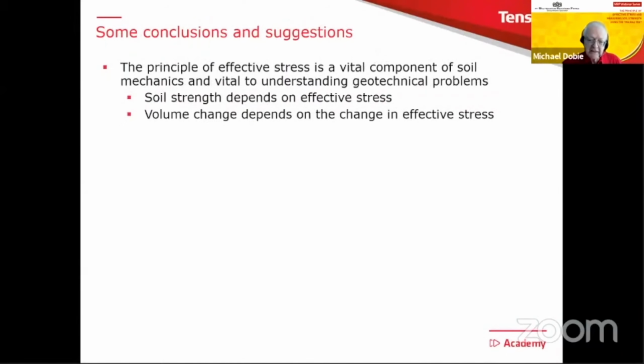So that's where I've come to the end. I did go slightly over 1 hour, as I thought it probably would, but I think there are quite a few important things, and I've probably gone through that rather more quickly than I should. But hopefully you can later on study the slides in the PDF version. But just a few final comments. First of all, the principle of effective stress. This is an absolutely vital component of soil mechanics, and therefore it's vital to understand this when looking at geotechnical problems. Reminding ourselves, soil strength depends on effective stress and volume change depends on the change in effective stress.